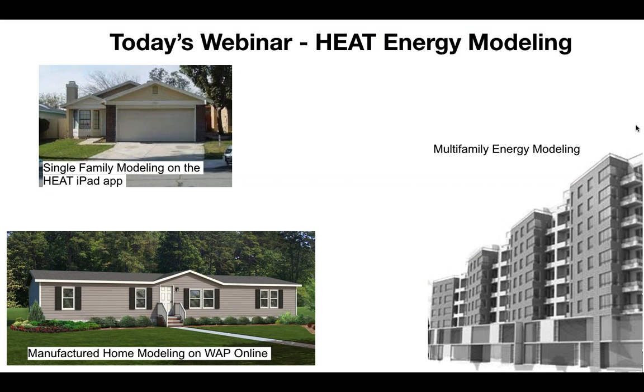So dealing with air infiltration differences at heights and then averaging them out over the whole building, finding the sort of middle point of air infiltration. So that's probably one of the biggest. The second biggest is the heating plant. You need to collect a little bit more information on more complex heating systems and integrated heating in DHW.